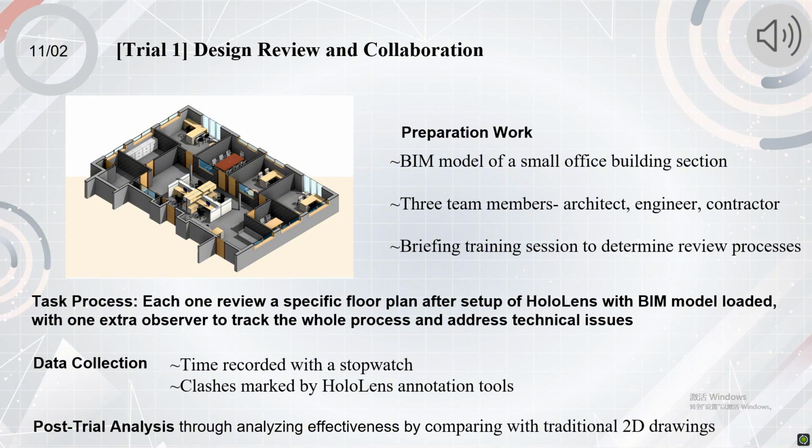review processes. Then, we were positioned around a large table in a well-lit conference room at the industrial center. The HoloLens devices were set up, and the BIM model was loaded onto each device. Each one was assigned a specific floor plan to review. In data collection, the review was timed using a stopwatch, and we used the HoloLens annotation tools to mark clashes. In post-trial analysis, a comparison was made with review time and clashes identified using traditional 2D drawings.